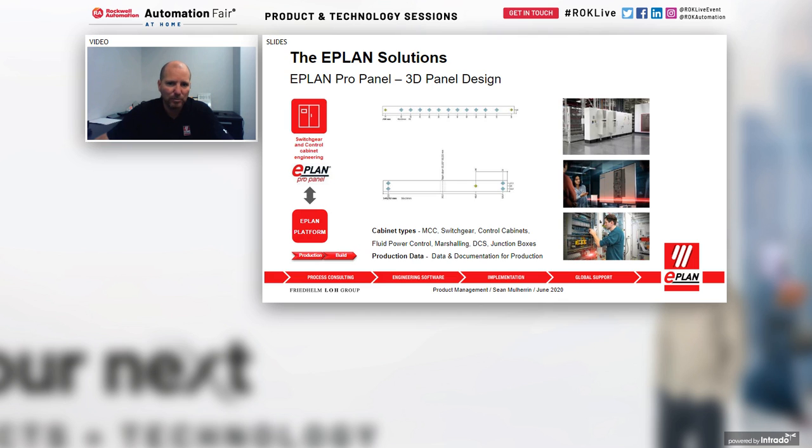Here you have a flattened view of your bus bar, for example, identifying where the holes need to be drilled in a specific bus bar. If you have a bending area where the bus bar needs to be bent, you'll have an identification, and it shows you how to manufacture that particular bus bar.